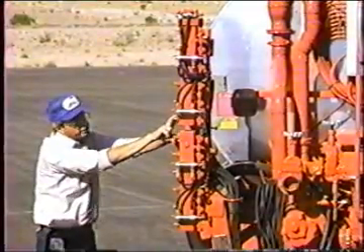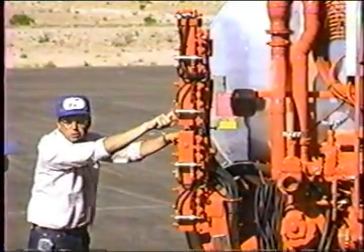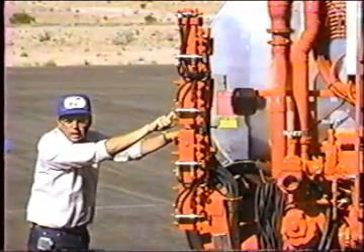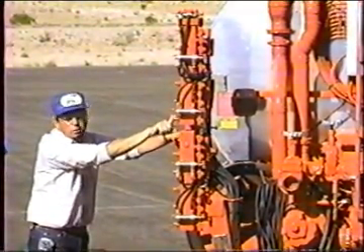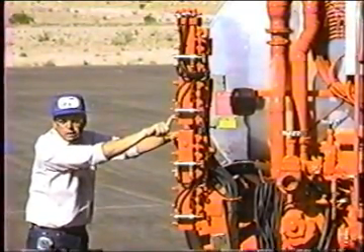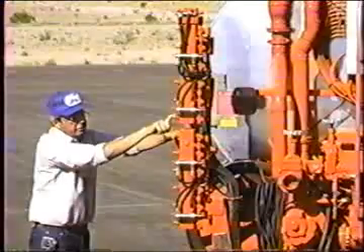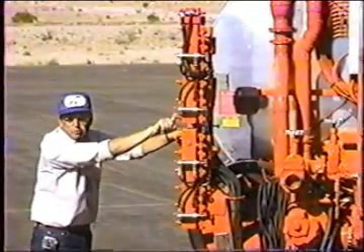But on this particular one, and this is the one you're operating, the last nozzle to get circulation is the inside of the outer wing. That's important later on when we actually do our clean out. We're going to want to check to see that we've got diesel throughout the spray bar. If we have gotten it to this last nozzle that gets circulation, that means we've got it everywhere.